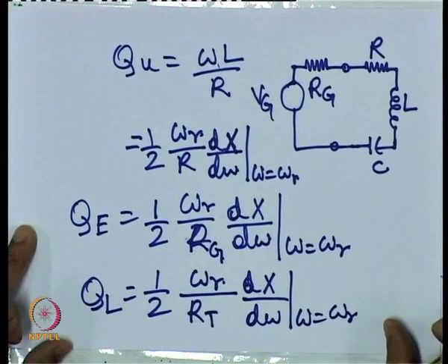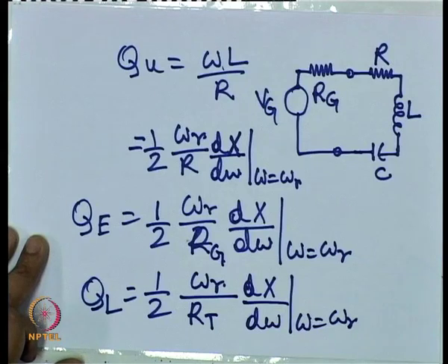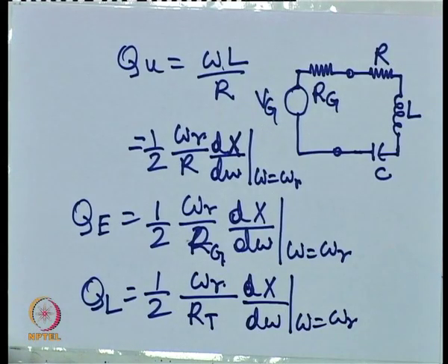Now, proceeding similarly, we can also derive the same relations for shunt RLC resonators. I am not going through the derivation, but it can be found, as I said, in the accompanying PPT files. And we will see that for a shunt resonator, we talk in terms of the admittances, susceptance, and conductances instead of impedance, resistance, and reactance. The relations for a shunt RLC resonator are very similar, except that the admittances are used in place of impedance and so on. You can go through it. Since they are the dual of these relations, I don't want to spend much time on them.